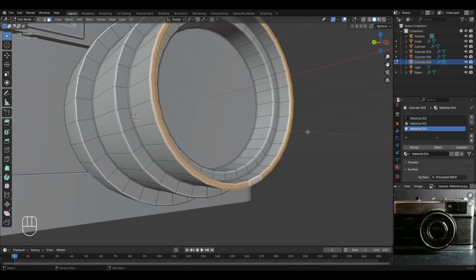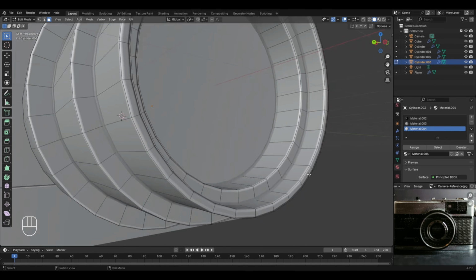selected. However, it might be possible that if you hold the Alt button and left click here, then some other face loop will also get selected. And the reason behind this is that the selected face loop will depend on the position of your cursor when you left click on the loop. For example, if I hold the Alt button and left click on this particular edge over here, then you will notice that it will always select the required face loop, and this is because by keeping the cursor over this edge while selecting the face loop, we are telling Blender that we want to select the entire loop of faces in the pattern of the selected edge.